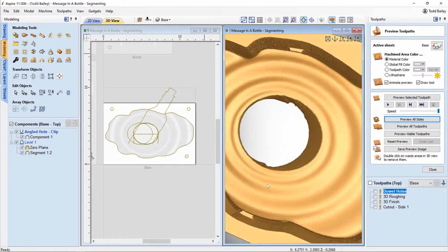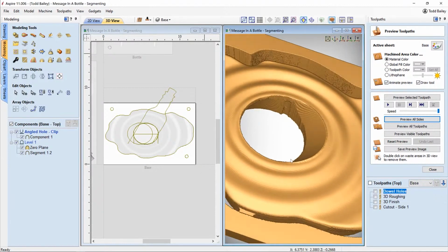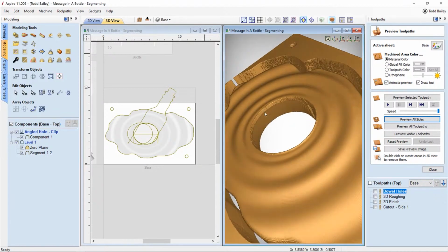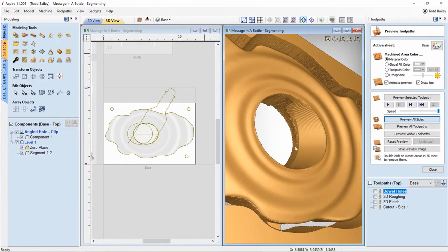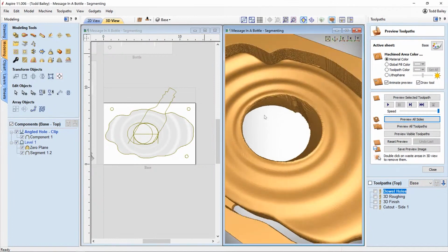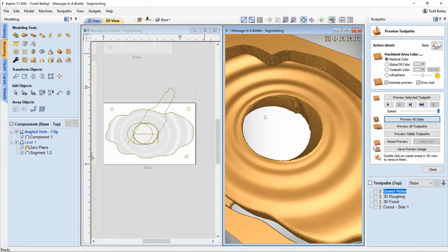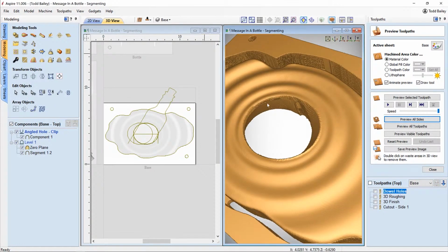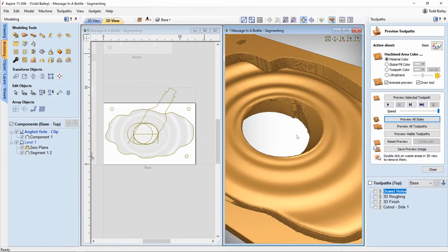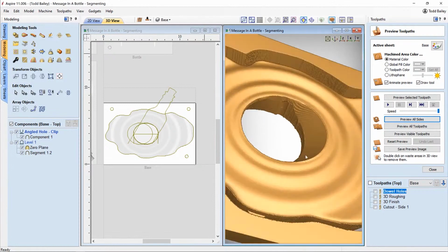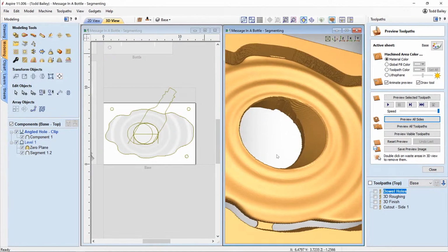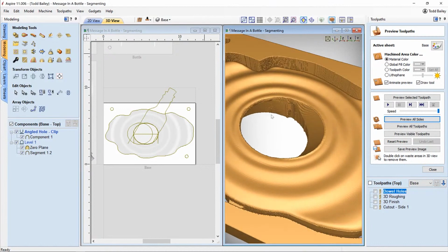Now, with this particular version of the file that you're going to receive, you'll notice that inside of here, there's a bit of a step on the inside lip and a bit of a step here on the other side. I purposely wanted those in there when I first developed this and when I cut it, because I didn't want this area to be too thin with somebody pulling the bottle in and out. So that shape that I made, instead of being 1.43 tall, it was 1.2 tall, okay? And that gave me a little bit of this extra meat here on the edges to work with, which may or may not work out to my advantage.